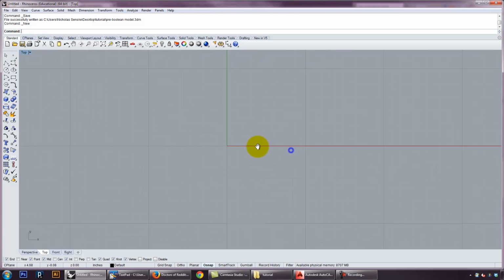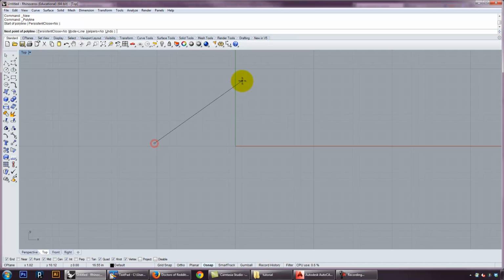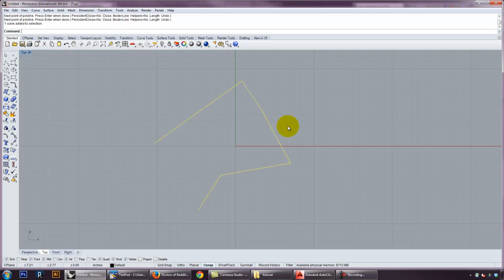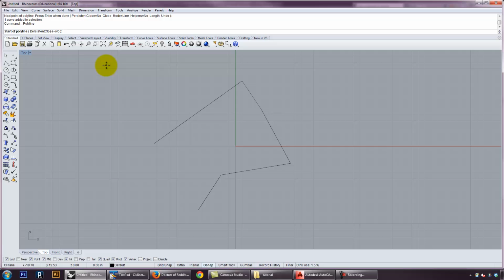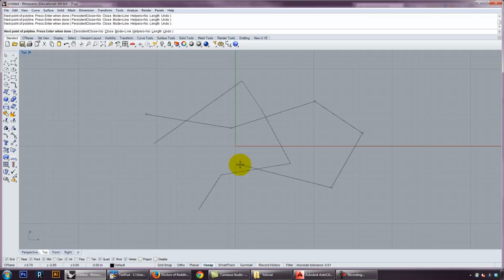I'm basically just going to start drawing in some plans here, just as a way to understand how these different tools work. So like in AutoCAD, the foundation of drawing is the line tool. You can basically click and make points. Every time you click, you get a new line, and when you're done, you right-click or you press Enter, and that will stop the command. Just like in AutoCAD, if you press Enter, you will get the same command launched again. So you can go ahead and make more than one line.